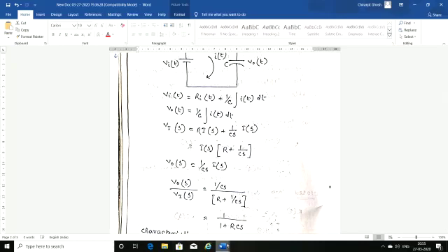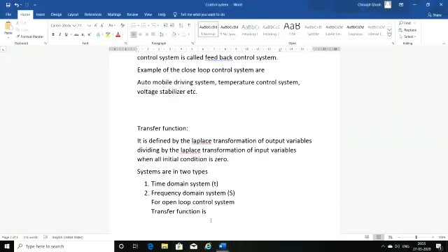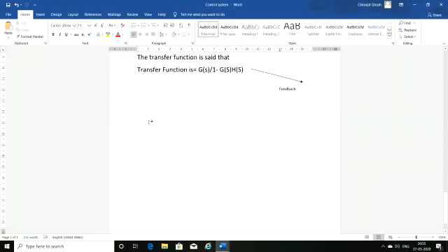So from the previous equations, we can write that the transfer function equals 1 divided by 1 plus capital R, capital C, capital S. So this is the transfer function of the above RC circuit.